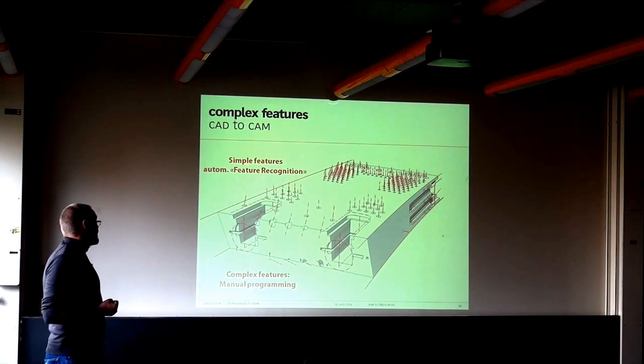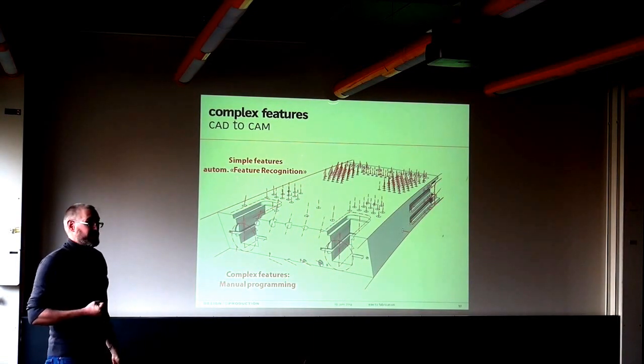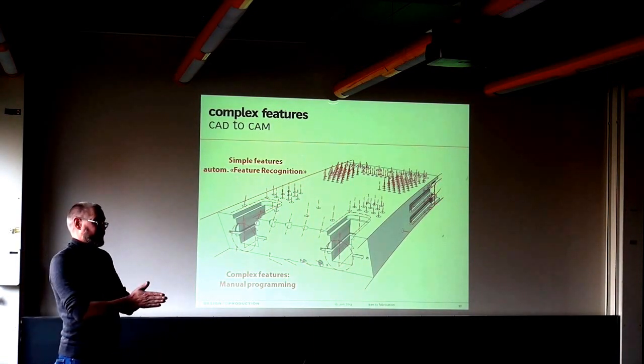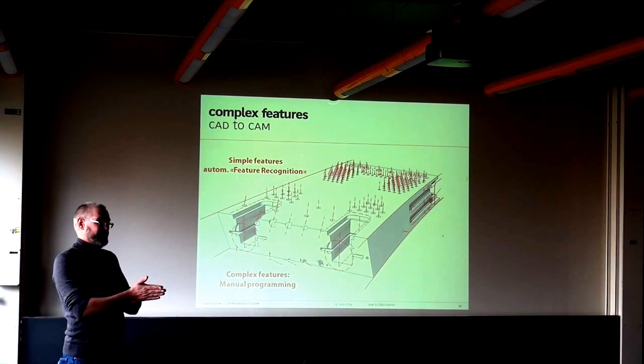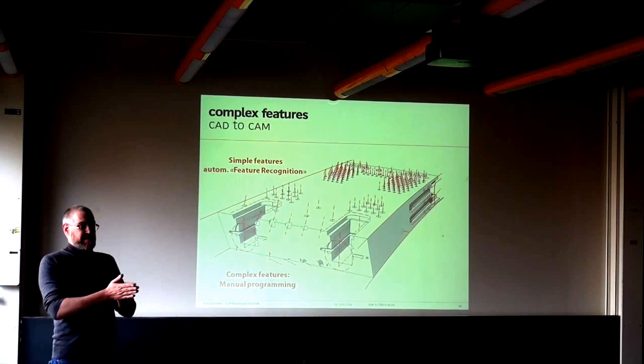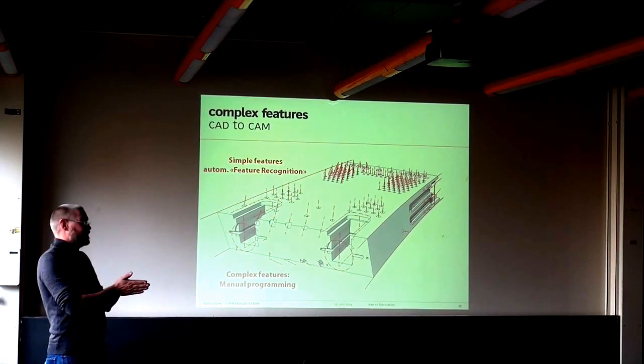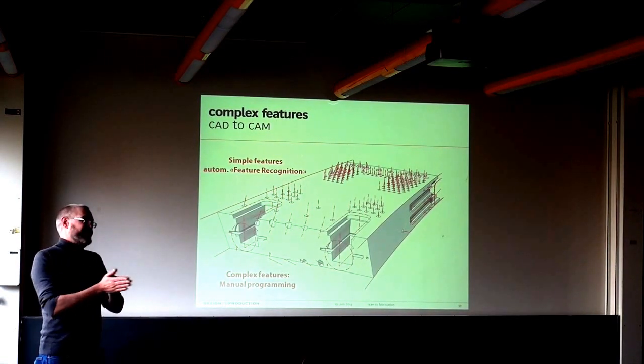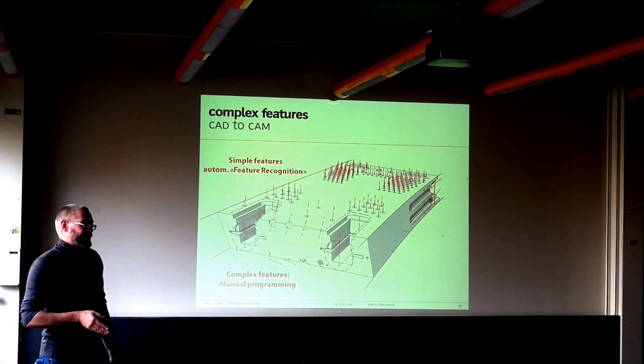Because the software then comes up with, oh, there's a Boolean operation with two surfaces coming together at a 0.5 degree angle, and I run into some numeric problems when I try to actually intersect that. Because if I have a bit of a rounding error, my intersection point is plus minus 2 centimeters off from where I want it. With which model do you work?